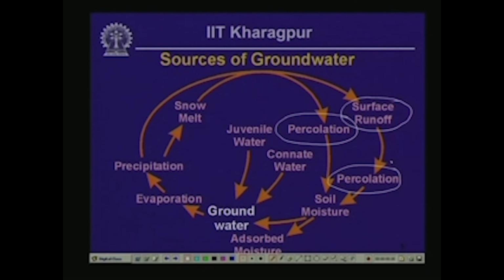A part of the soil moisture is going to be available in the form of groundwater, and another part is going to be locked within the matrix in the form of adsorbed moisture, which is tightly held by chemical bonds on the surfaces of the soil particles, and another part is going to be unavailable for use because it is going to be trapped within non-interconnected soil voids, as we are going to see in the next little bit.